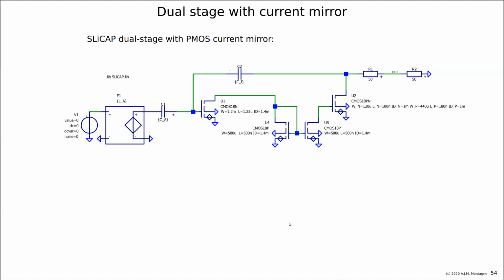And you see, the nice thing about SLIDECAP is you don't have to worry about the implementation of the biasing. It's something I simply don't want at this stage, because any effort I put in biasing of something that is not feasible at the end is lost effort. I first want to have a signal path that is feasible, and if I can achieve the bandwidth, if the circuit is stable, if the frequency compensation can be applied so that it is stable under all conditions, then we have a reason to go for the next step in the biasing.